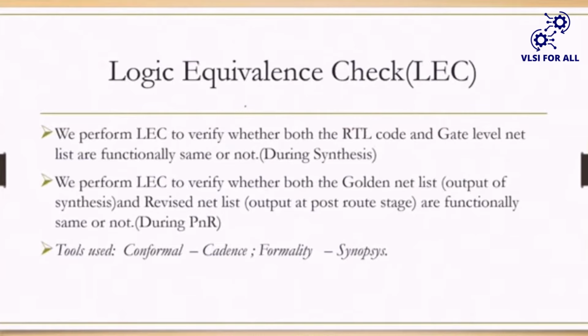That is very important. I'm not sure whether the functionality is the same or not for the design obtained from the RTL team compared to the design of the present situation. So I want to check, and that check is called logic equivalence check.